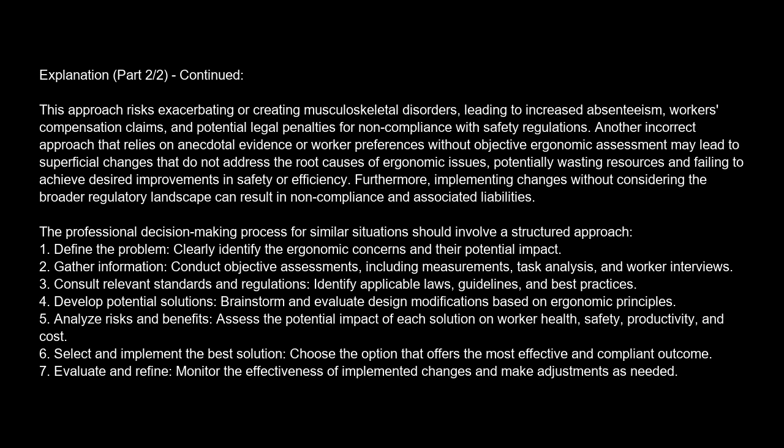4. Develop potential solutions. Brainstorm and evaluate design modifications based on ergonomic principles. 5. Analyze risks and benefits. Assess the potential impact of each solution on worker health, safety, productivity, and cost. 6. Select and implement the best solution. Choose the option that offers the most effective and compliant outcome. 7. Evaluate and refine. Monitor the effectiveness of implemented changes and make adjustments as needed.